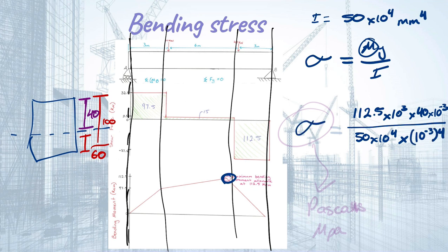And that'll give you your value. You pop that in the calculator. Oh, and it's also important to note that your ultimate bending stress calculation will end up in pascals. And it's usually a big calculation, so often it'll be in megapascals.